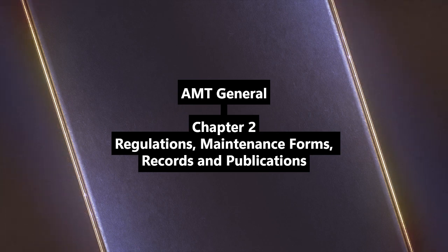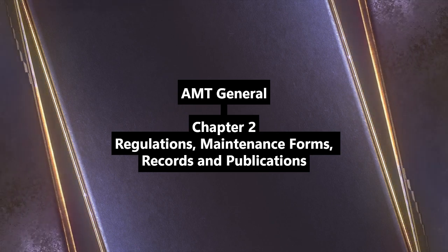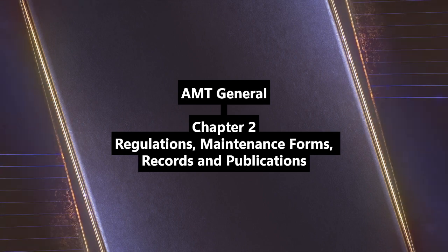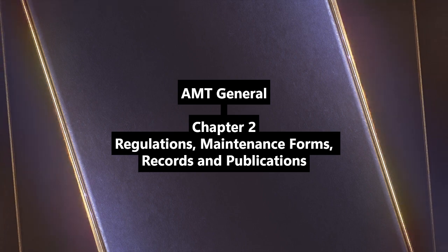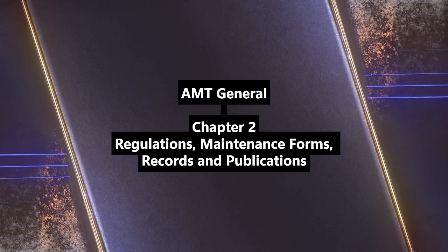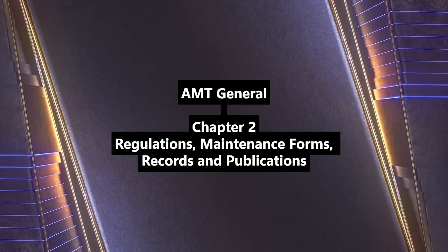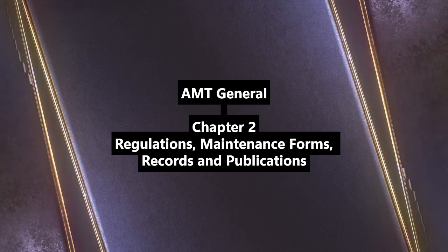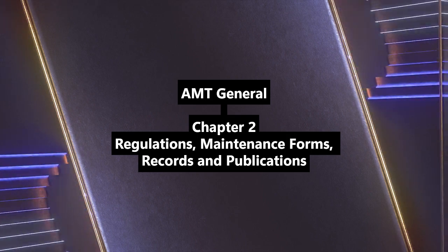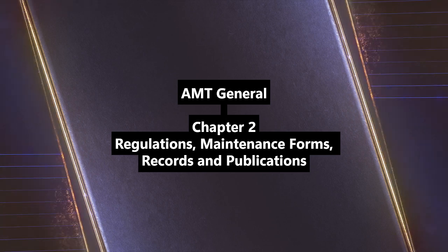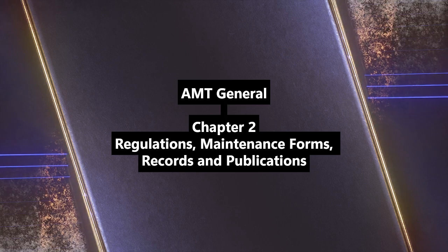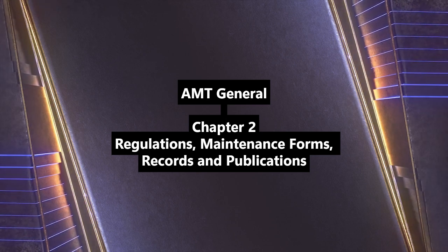Example. CAR 3, Airplane Airworthiness: Normal, Utility, Acrobatic, Restricted, was the basis for today's Part 23. Covered flight, structure, design, power plant, equipment. Think Piper PA series, Cessna 182, 195, 300. Many were CAR 3 aircraft. And watch out, CAR can also mean Canadian Aviation Regulations. Good point, yes. Context matters. There's also CAR 4A from 1936, basis for many 30s, 50s planes. Later CAR 3 focused on small planes, CAR 4B on larger ones.